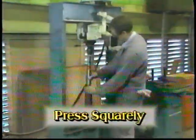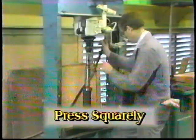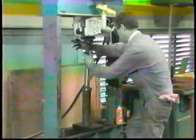If you do press on the wrong ring, the races and rollers are likely to be dented or brinelled by the force of the press. Press squarely. The press must be arranged to push the bearing on the shaft or into the bore absolutely straight. The ram must be lined up precisely with the shaft or the bore, and the force must be equal around the full circumference of the ring.